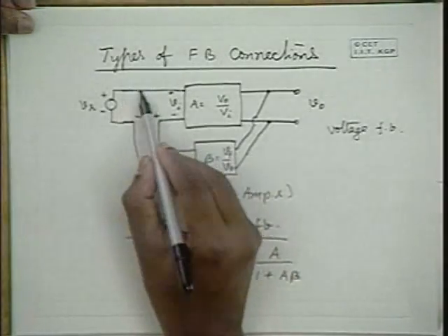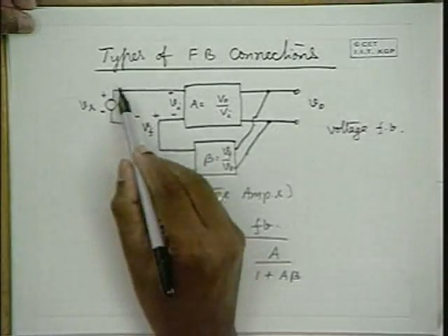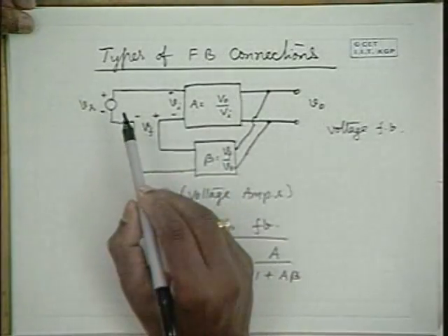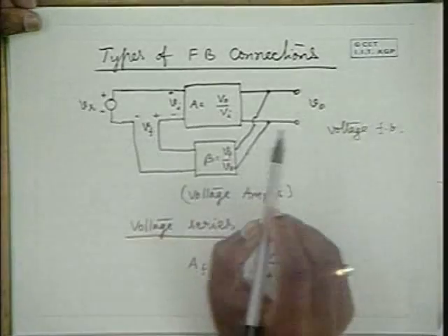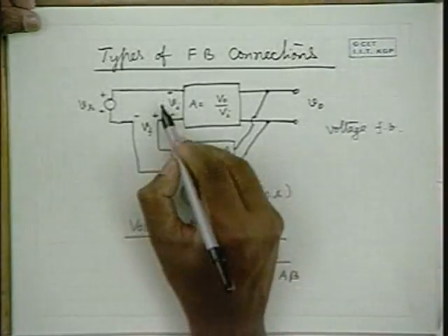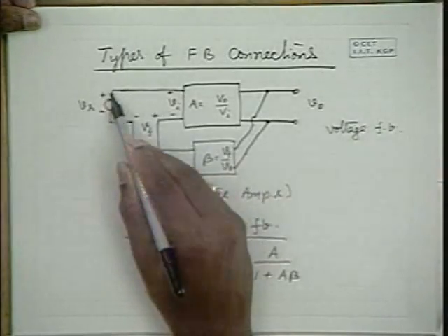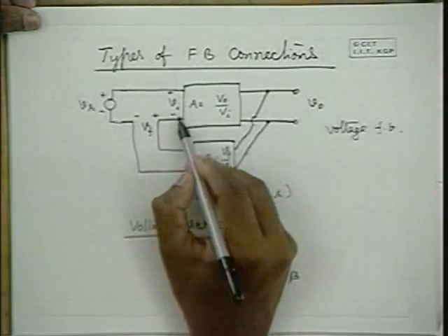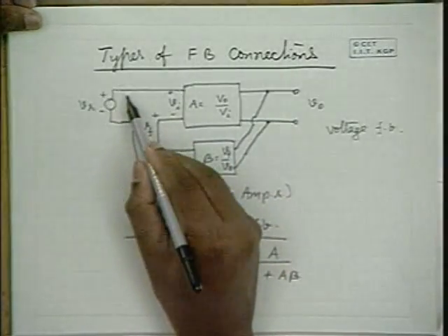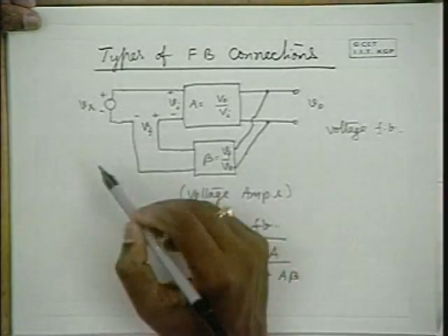500 ohms. Now the same current flows out of the source. So here 0.5 volts divided by that current is 500 ohms. Now it is 1 volt divided by the same current. So with respect to the voltage, the current that is drawn is half that of this one. Therefore, the input impedance is effectively increasing. Say whatever is the current that is drawn for 0.5 volts will now be drawn from a 1 volt source. 1 volt divided by that current, and 0.5 volts divided by this current. 0.5 volts divided by this current is Ri. So 1 volt divided by this current is going to be 2 Ri. So Ri is effectively increasing in this connection. It's getting doubled in this particular example.